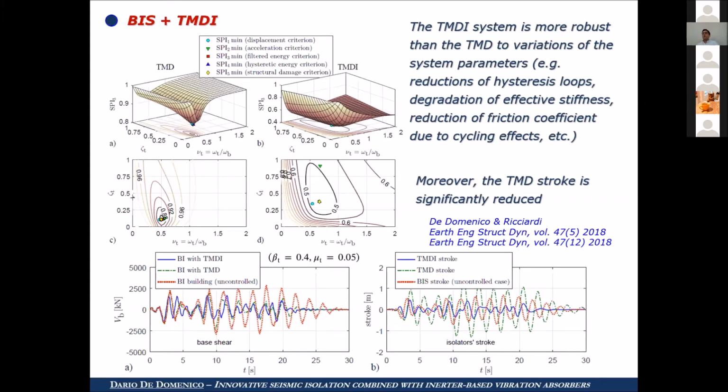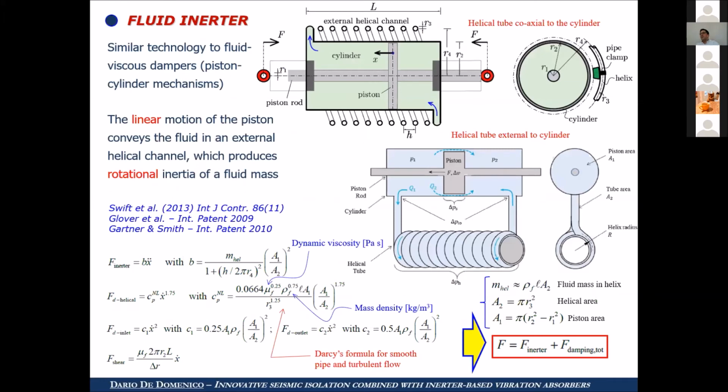But the most interesting application of this concept of the inerter is the fluid inerter. I mean, the fluid realization of the device. If we have a look at this device, it has many similarities with the classical fluid viscous dampers, the most commonly used dampers in the world, which imply a transfer of a silicon fluid from one chamber to another to dissipate energy.